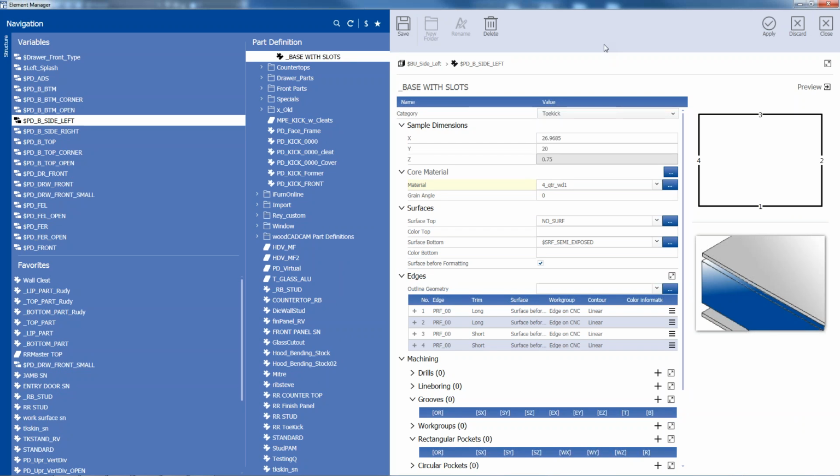All right, so how wide are these slots? I want to have them be half-inch diameter cut, starting 2 inches from the edge on each side, and from the bottom. I'm just gonna make a groove with a 1/2 inch bit. So the bottom one, I would like to have 3/4 of the floor, 1/2 inch groove, then 1/2 inch space, 1/2 inch groove, 1/2 inch space, and 1/2 inch groove. Okay. So it's going to be centered on the board.